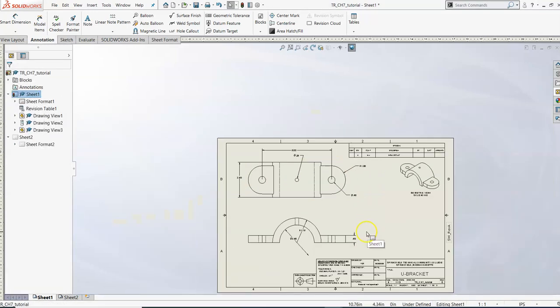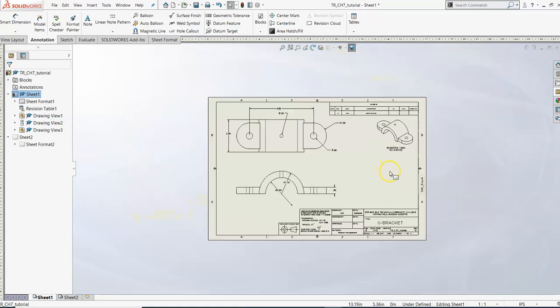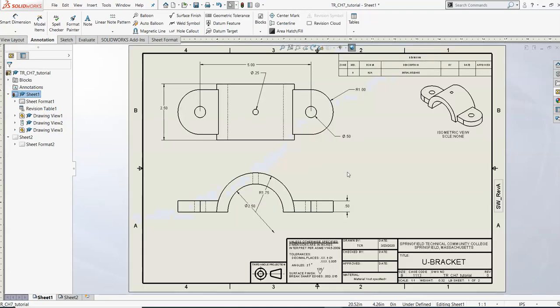Okay, you just want to make sure that it's clearly legible for right now. We're not gonna get into too crazy of drawings. All right, so if you see what I did there, if you zoom all out, a simple F, and it fits it to your screen for you perfectly. Okay, you could have also gone into Smart Dimension and dimensioned all these on your own. Okay, but there's a few things that we do have to fix.